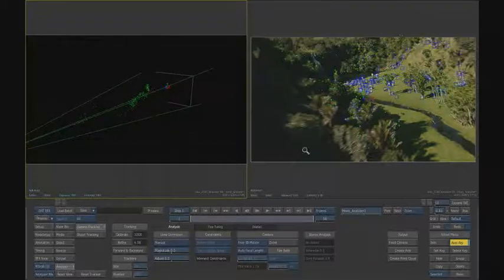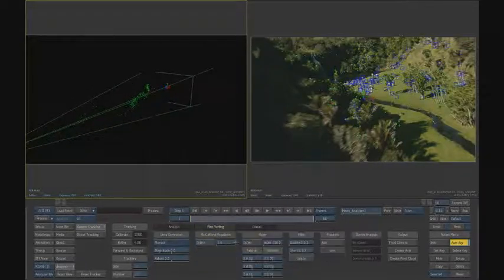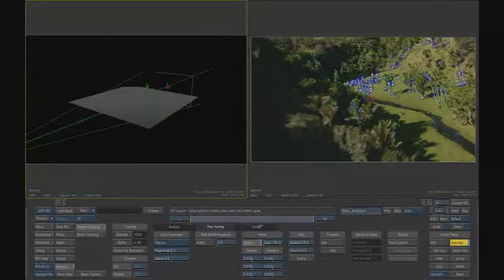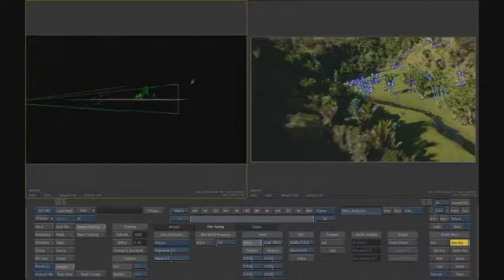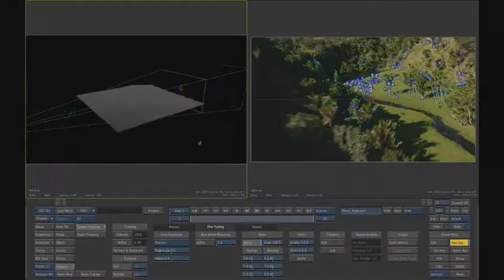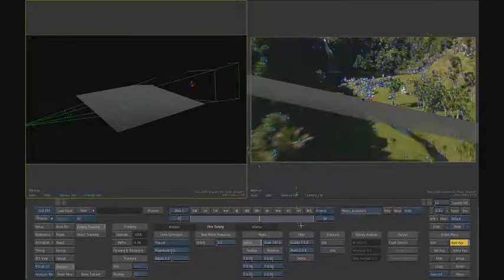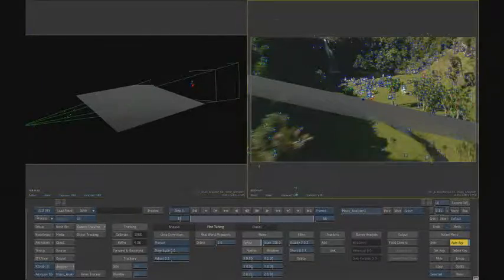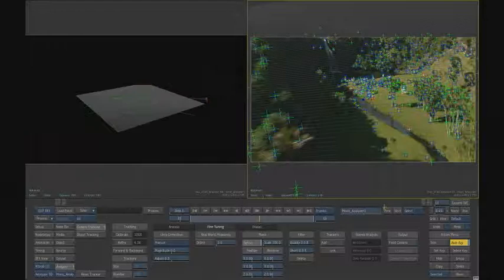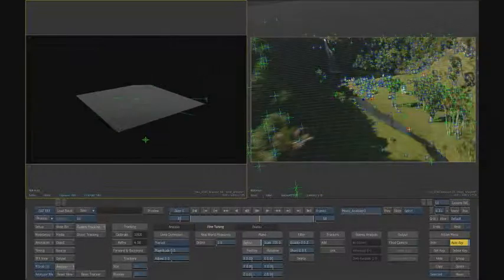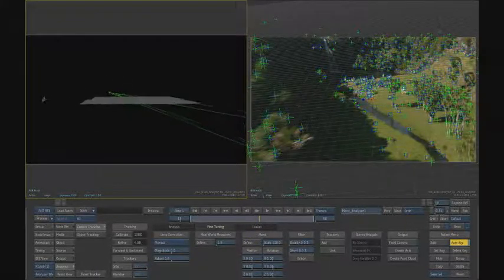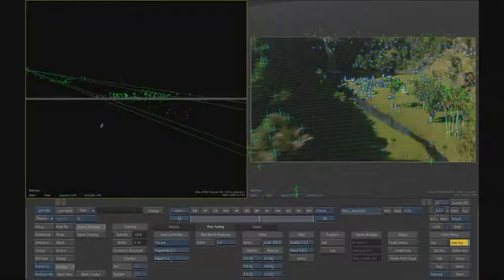What we'll do with this data is we'll refine it a little bit more via defining a ground plane, as we call it. So if I turn on my plane here, you'll notice that by default over here the camera is sitting on the ground because it doesn't know whether it's up or down, or essentially that it's in a helicopter. So we can further define our scene in these terms, which is very useful when working with a CG artist to lay down geometry. So we'll start here, we'll pick 3 points or more to define a ground plane, and that really locks down the grid. So you can see over here that this is just a neat way of defining how things are going to look. So now you can see that we are now in the air and the ground is really the ground.